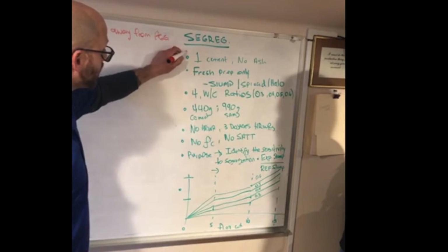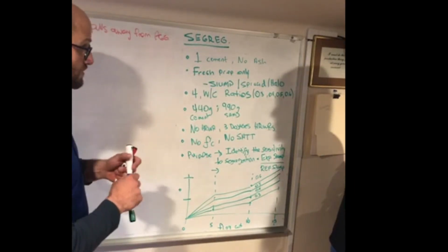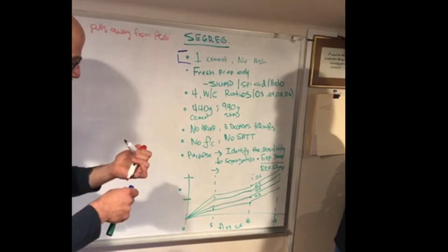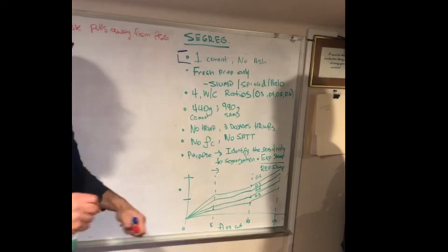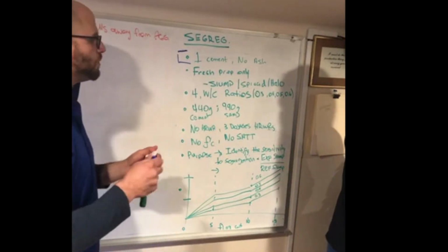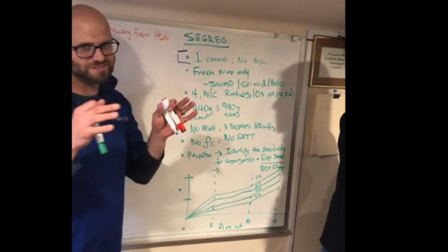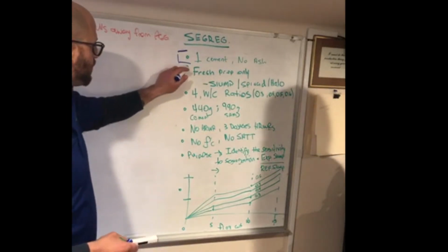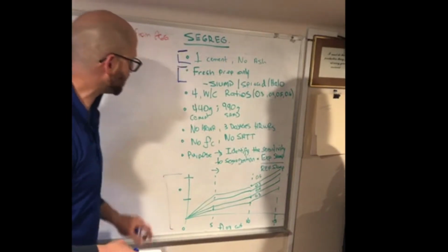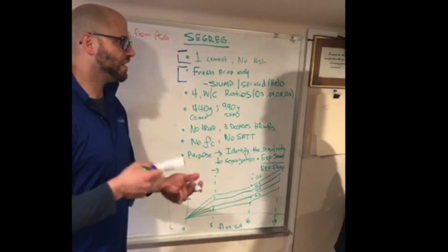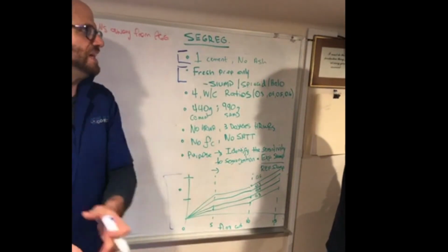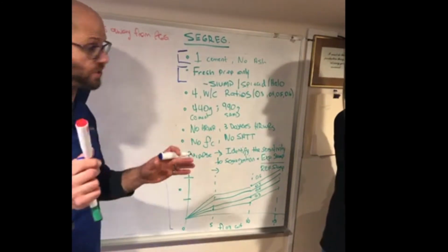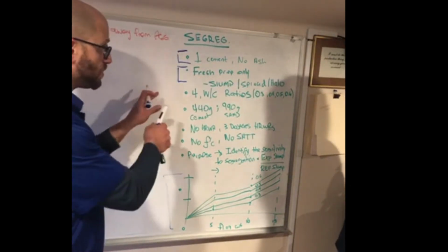So the next thing is we're going to make this really, really simple for this study, right? So just going down the list. We're going to do a Portland cement only mix. There's nothing wrong with using fly ash or supplementary cementitious materials, but we don't want to confuse this. We're doing 2 parameter changes, and that's enough. We're only going to be looking at fresh properties and limiting to it. We're going to come up with a pretty graph like this, but we're not going to be doing strengths on this specifically. We're going to be taking some mixes into that segregation zone. So we're just going to disregard strengths for this project and this project only. Any questions about that? No.